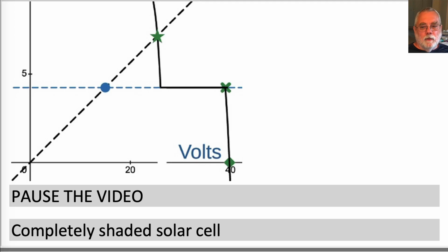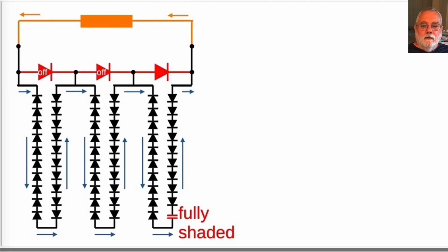This was the original motivation for the bypass diodes, to bypass a string that was not producing current. It's a little confusing to see how the reverse bias would develop. Imagine the partially shaded solar cell becomes a capacitor, the space charge layer, as it becomes fully shaded.